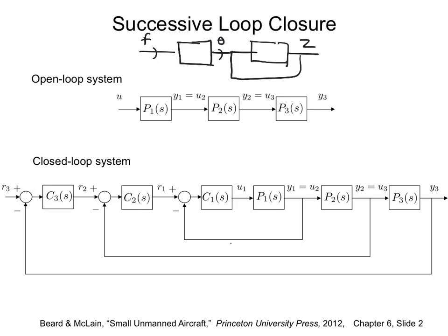So you design a PD for that, and then a different PD for this one. So two loops closed. So you always start with the inner loop, which is where the direct control is. Inner loops are always faster because you want to separate. Like for example,